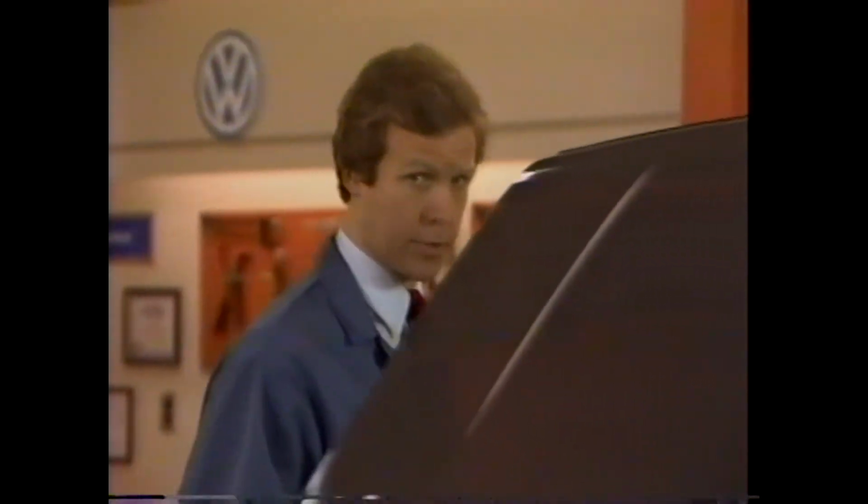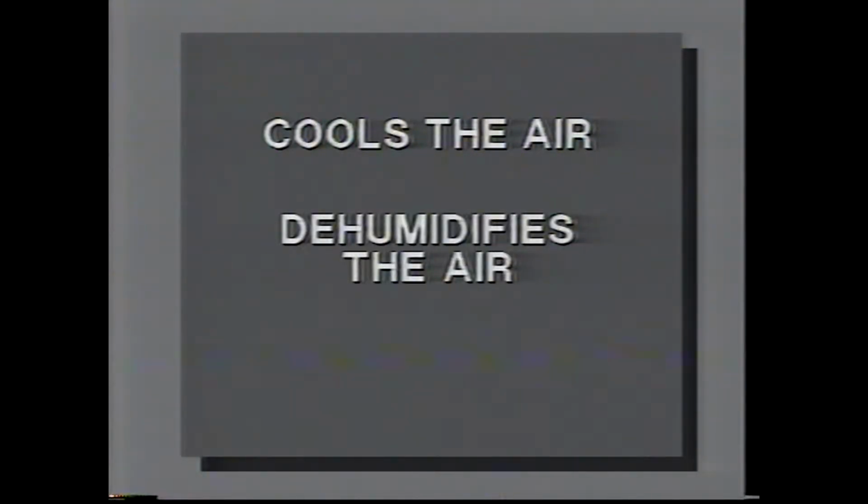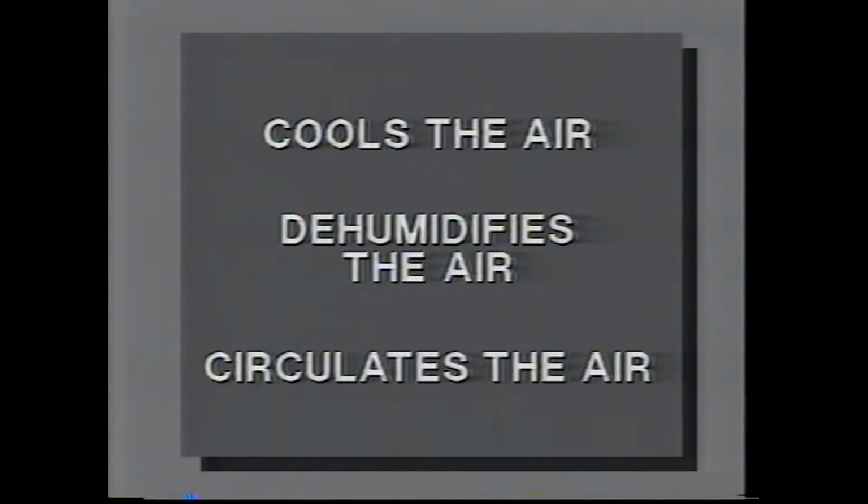And welcome to the third Volkswagen Communications Network service release covering the air conditioning system. Air conditioning is no longer a luxury item in today's automobiles. It improves the total driving environment and increases passenger riding comfort. The air conditioning system has three principal functions. It cools the interior air, removes moisture or dehumidifies the air, and circulates the cool, dehumidified air inside the car.